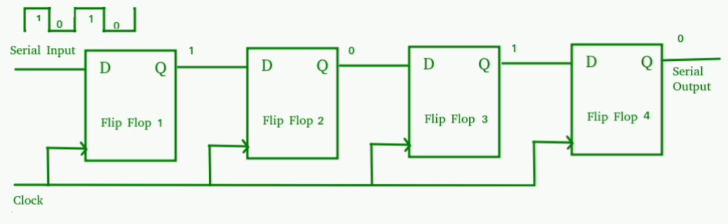F clock is less than or equal to 1 by n TPD flip-flop. Maximum clock frequency, f clock, m equal to 1 by n TPD flip-flop. Disadvantages of ripple counter: decoding error is present due to propagation delay of flip-flops, that is TPD flip-flop.